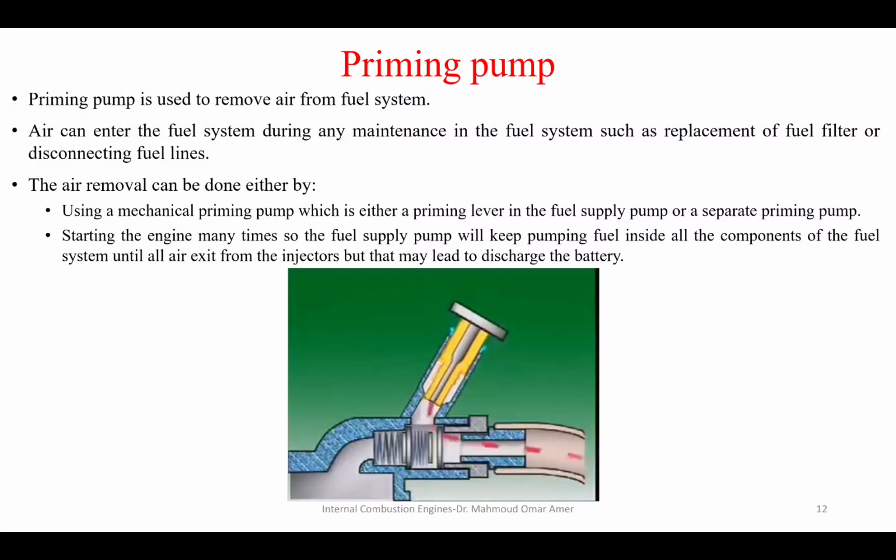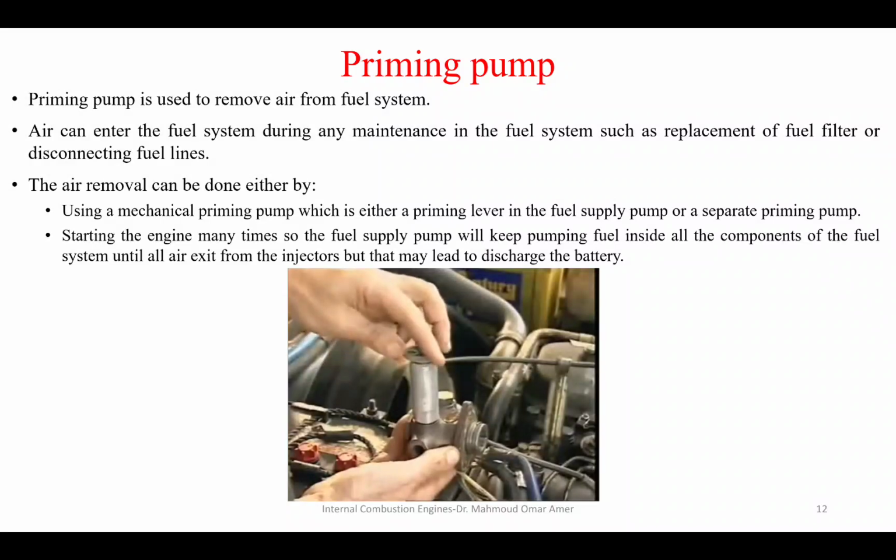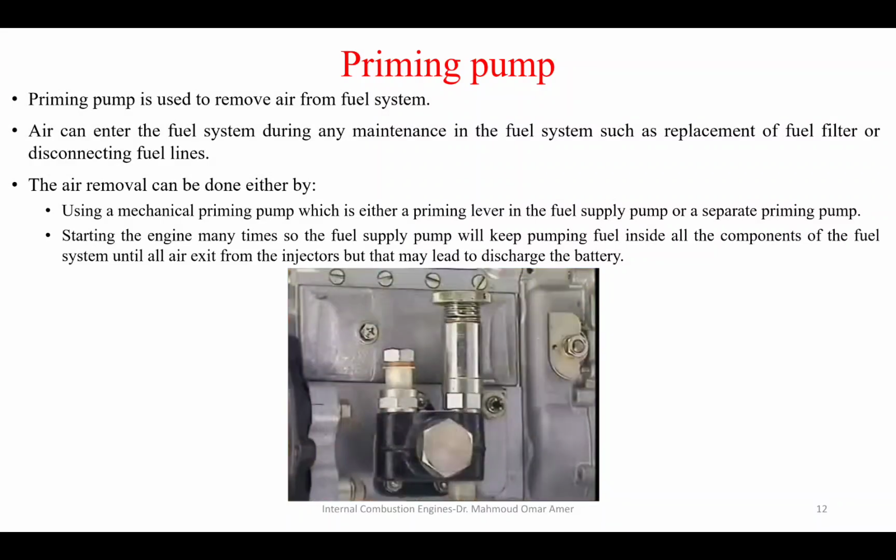Pulling the primer plunger increases chamber volume, which decreases the pressure in the chamber below that of atmospheric. Fuel in the tank is forced along the fuel lines through the inlet check valve and into the pumping chamber. Pushing the plunger into the barrel decreases the volume in the chamber, which forces fuel out through the outlet check valve. When the priming pump is not in use, the hand knob must be screwed closed. This stops fuel leaking out past the plunger and also stops air leaking into the priming plunger barrel.